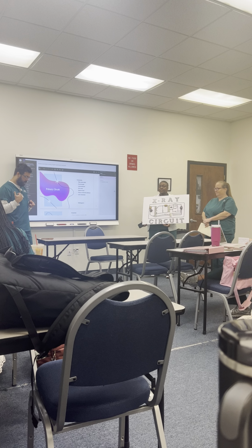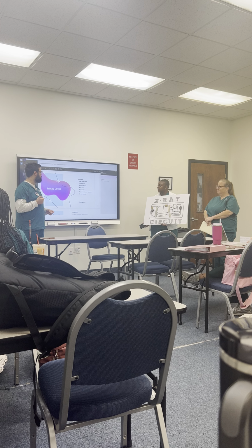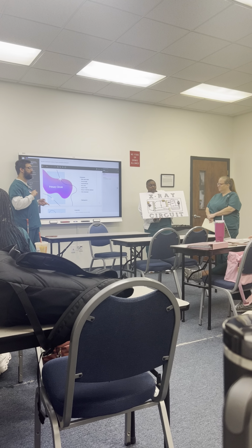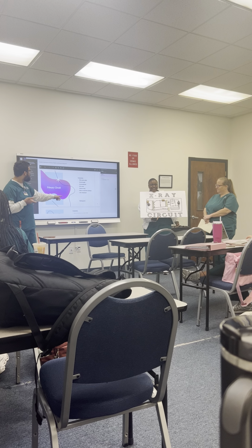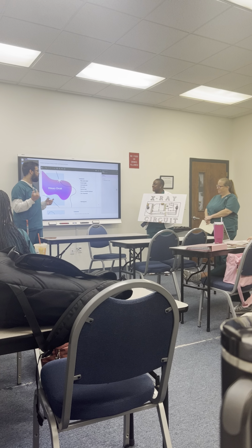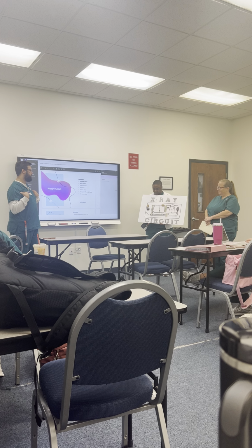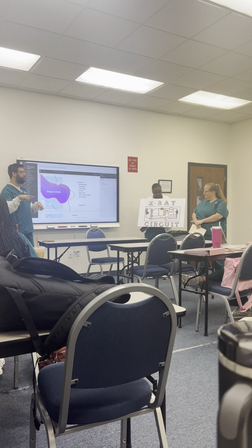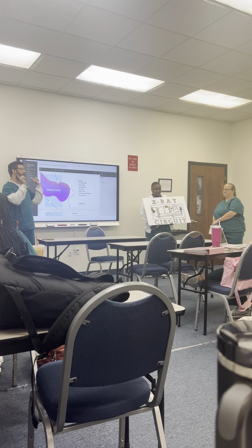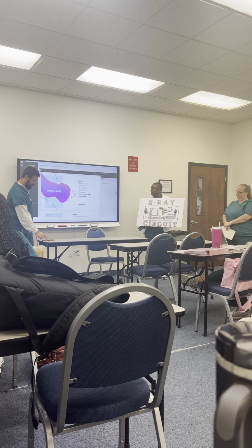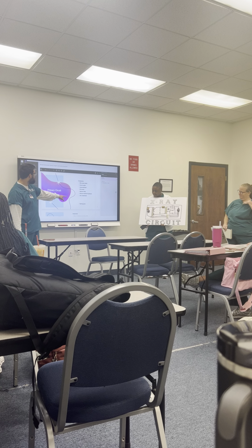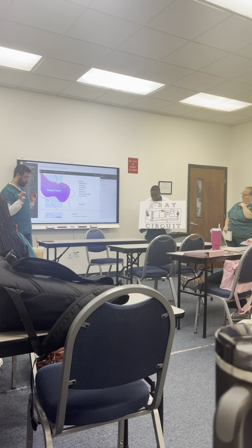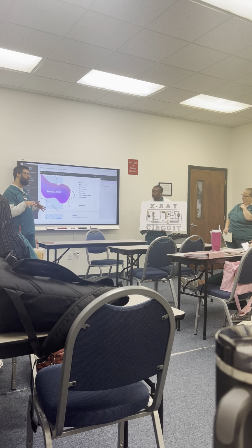And then the KVP meter is just reading the KVP to make sure that it's set to what it needs to be. We have the exposure timer, which is kind of the same thing, but instead of the KVP, it's making sure that it's doing the exact time that they set on the panel. There's the step-up transformer primary. On my side, it has fewer coils than the secondary side, so that it can step up the KV and lower the mA. And then we have the line compensator, which will just stabilize the voltage at about 220 volts.